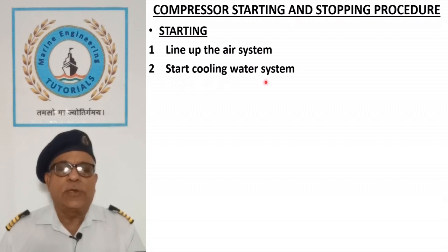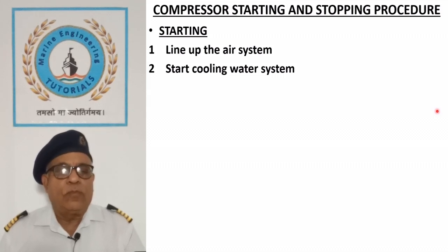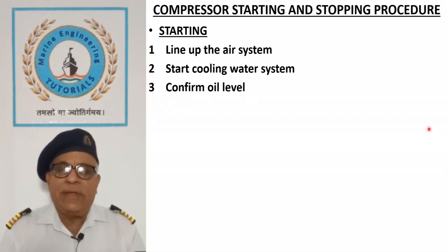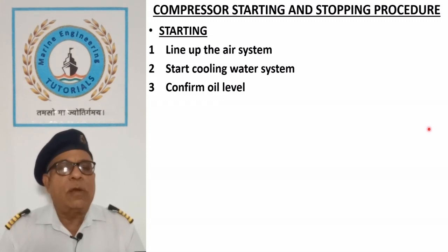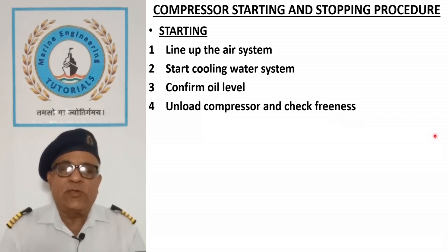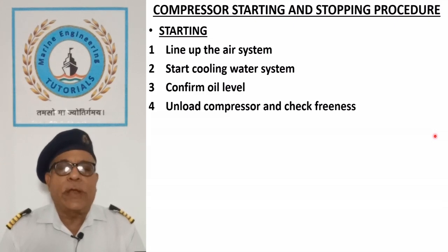Start cooling water system. Ensure that cooling water valves are correctly positioned and water is circulated through the compressor. Confirm oil level. Ensure that oil level in crankcase and lubricator are normal. Unload compressor and check freeness. Ensure that drains are open and check freeness of the compressor by hand turning.